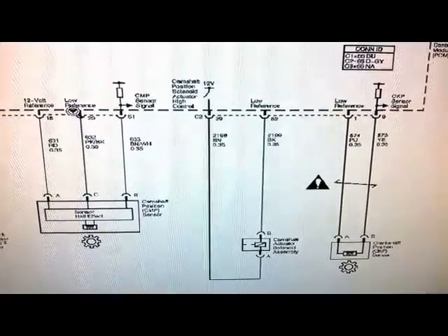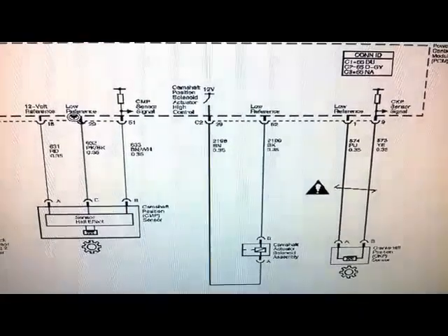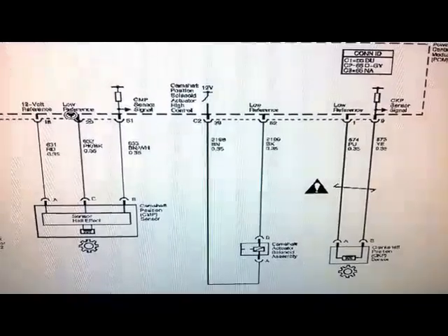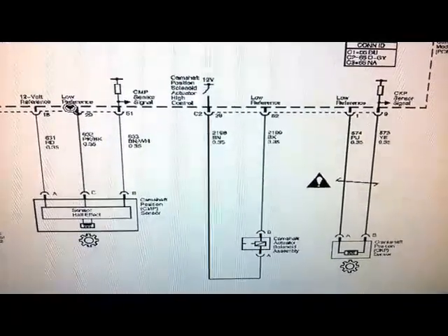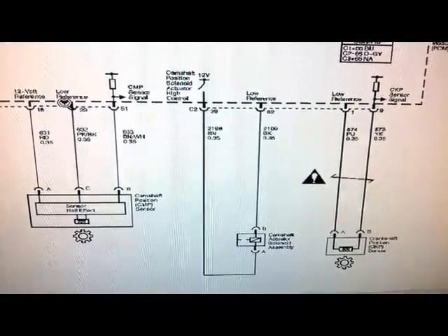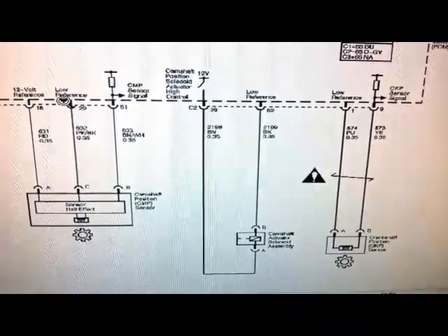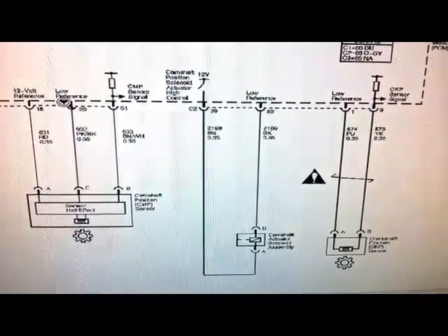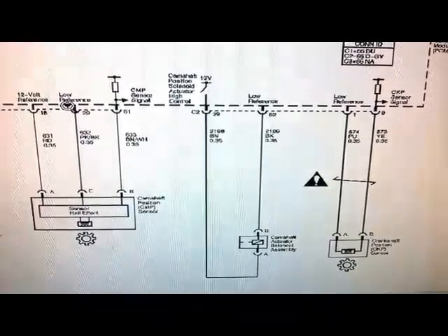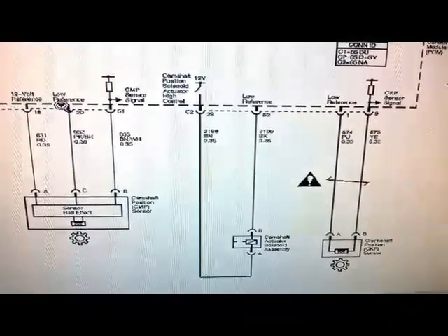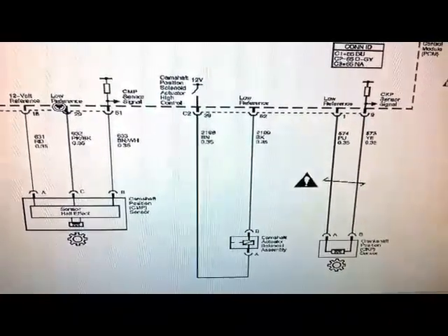Since both wires are going to the computer, and on the brown wire it's telling it that it's the actuator height control, this tells me that this is probably a power side switch solenoid. So with the key on engine off, both wires should read approximately 0 volts. So next step is to go out there and perform these checks with the voltmeter.